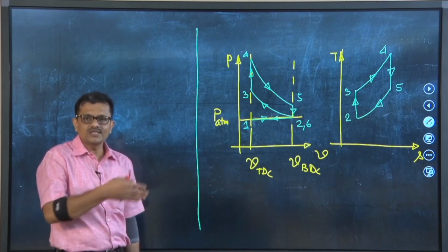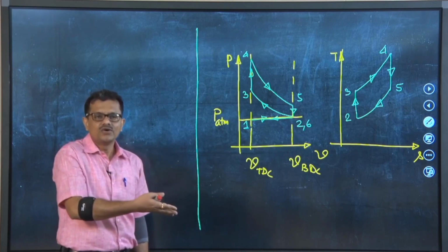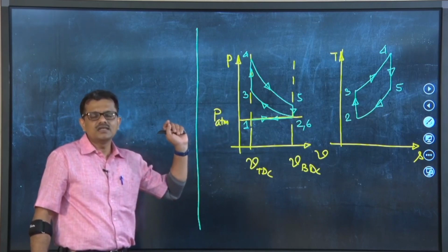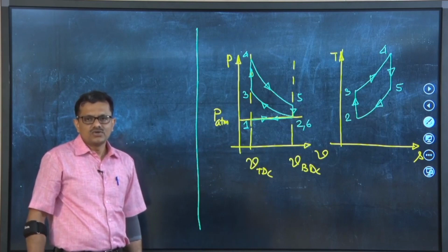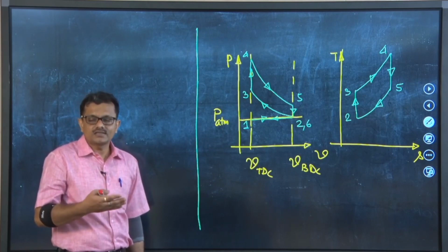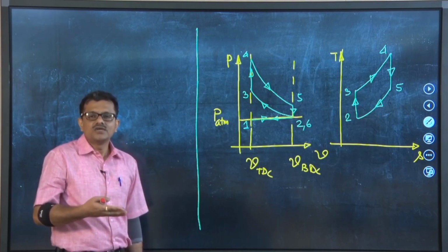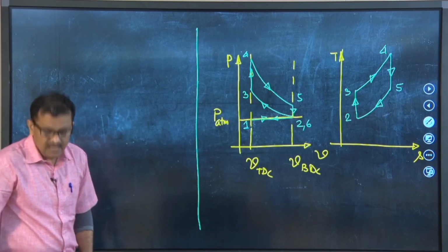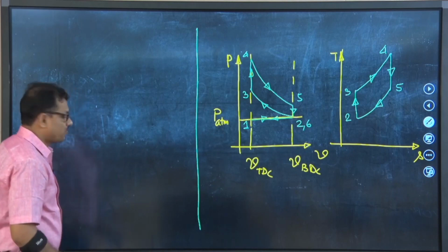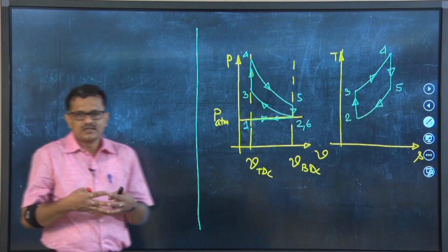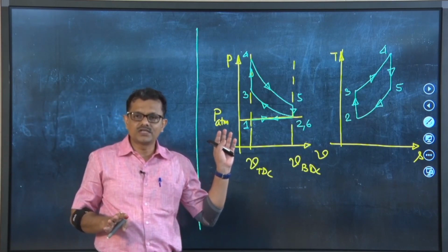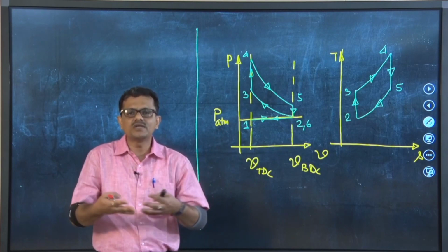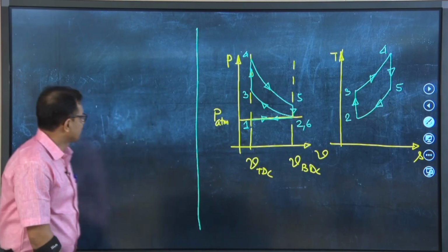So, when you are trying to analyze all the processes by using an air standard cycle, we can assume that the working substance in the SI engine is an ideal gas. We are considering the working substance to be an ideal gas for the analysis, and it is due to the fact that we are assuming that the cycle is approximated by an air standard cycle. In reality it is not purely air, it is an air fuel mixture during the compression stroke. Again, for the expansion stroke, it is not purely air and fuel, rather it is several components of the combustion products.